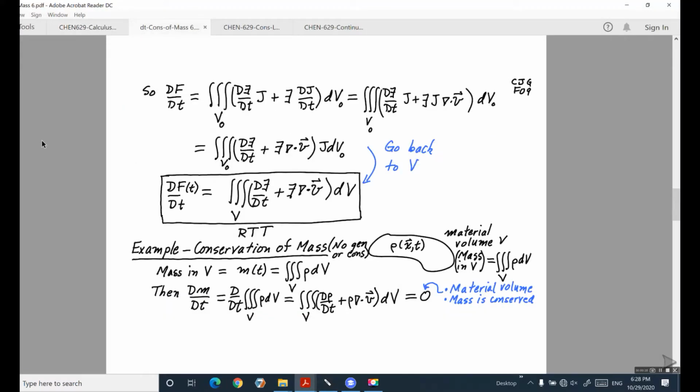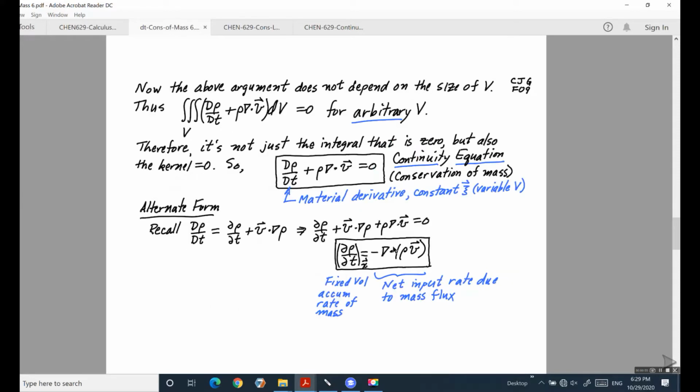Then later on, we drew the Reynolds transport theorem. Any extensive property, like the total mass of your system, changing with respect to time, the material derivative, is equal to that one, again with the intensive property. So we apply that to the conservation of mass in here, and we obtain the continuity equation. This is the first form, and the second form we can represent like this.